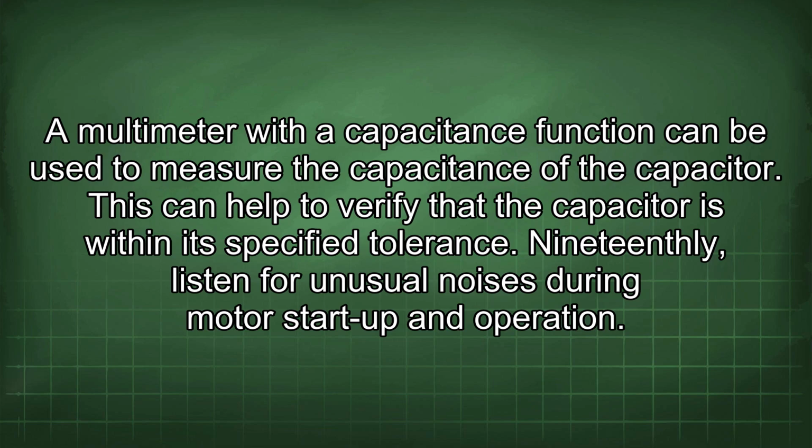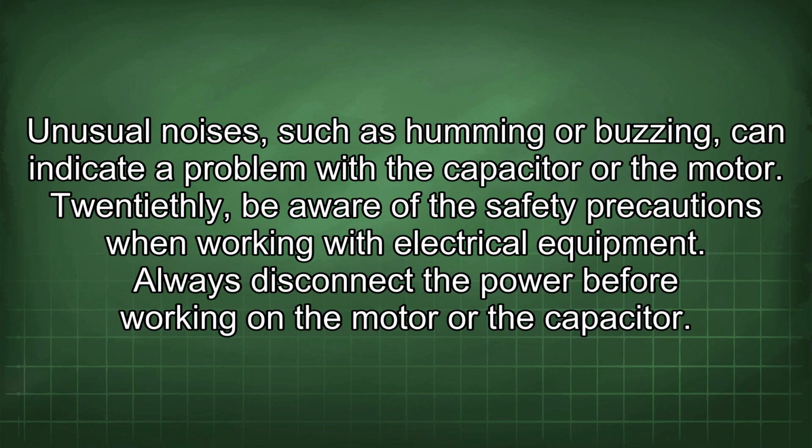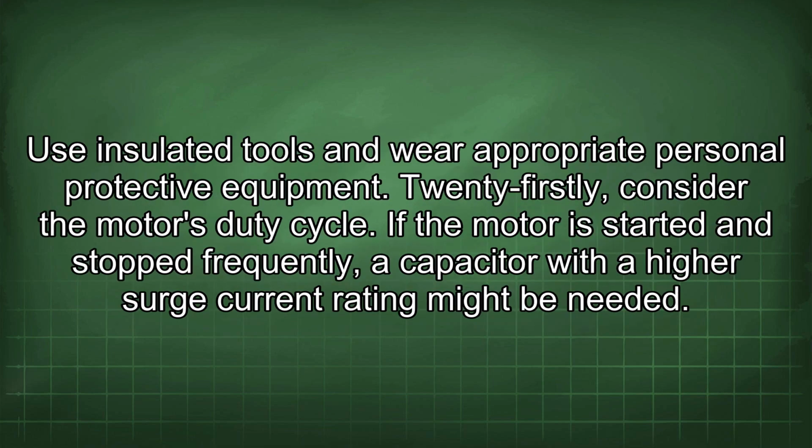19th, listen for unusual noises during motor startup and operation. Unusual noises, such as humming or buzzing, can indicate a problem with the capacitor or the motor. 20th, be aware of the safety precautions when working with electrical equipment. Always disconnect the power before working on the motor or the capacitor. Use insulated tools and wear appropriate personal protective equipment.